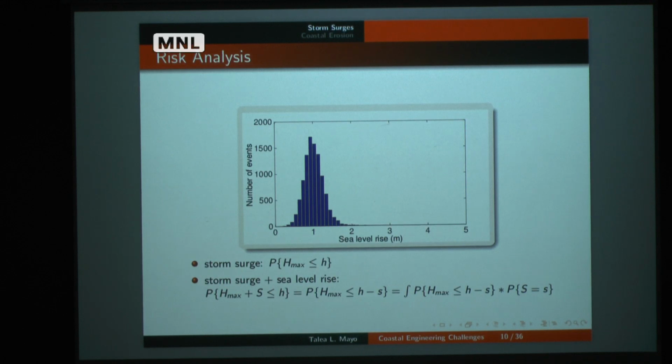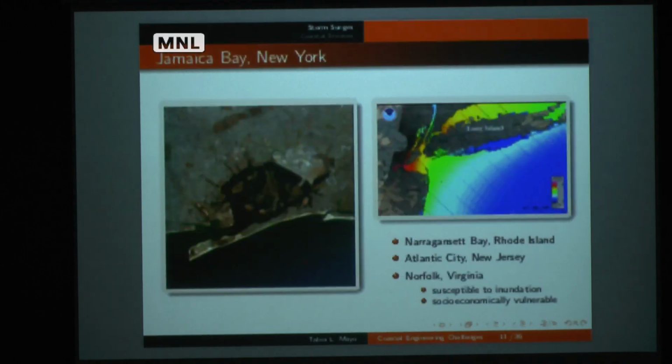Okay, so then we can get the distribution for the storm surge height, but flood is also dependent on sea level rise. Sea level rise is a local characteristic, so you also have some distribution there. Usually in the news, we hear about mean sea level rise or global mean sea level. But if you're studying a particular location, you really should look at the local sea level rise, so what's expected based on the properties there. Here we didn't model this distribution, we just used a discrete distribution. We can compute these joint probabilities to get the return curve for the total flood.